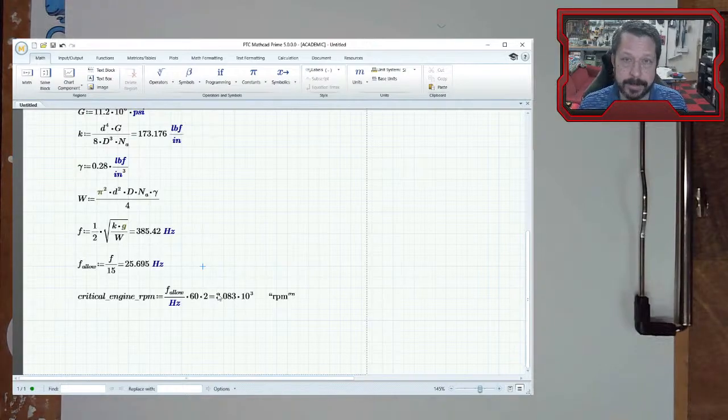If you have a tachometer in your car, then it will have a red area where if you get the engine rotating that fast, bad things are going to happen. These are some of the bad things that could happen. You could have valve float where you hit the fundamental frequency, or you're getting close to it, still 15 times away from it in our calculation right here.